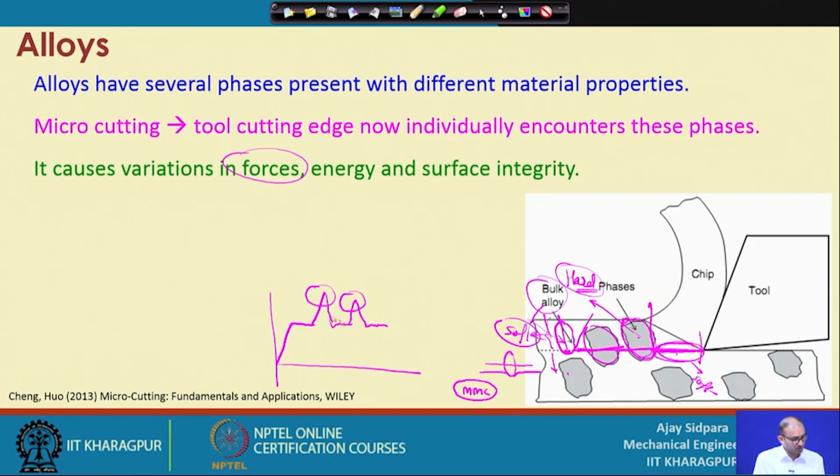The only thing is that we should analyze this signal correctly, because this is not the only signature by which you get this signal. There may be something else. Suppose you have an end mill cutter with 4 edges, and after some time one of the edges is broken, so that it is not able to do any cutting. When it rotates, it will create one signal, and this particular edge will not give any signal because it is already broken.